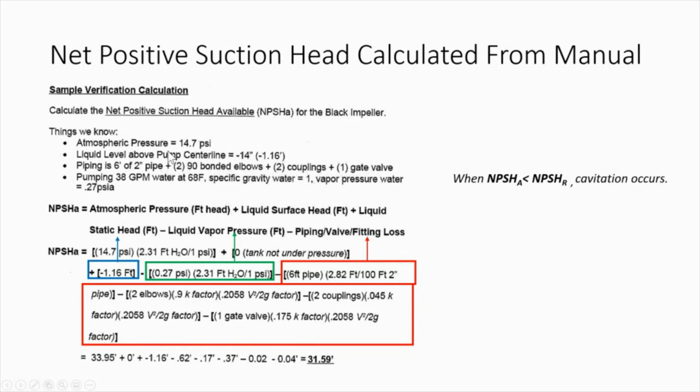But just remember one thing, that whenever you do a math, always keep your units consistent. For example, you have over here PSI, but let's say your static head, it's in feet, right? So you need to convert this feet thing into inch. Only then you can solve the math. So yeah, if you plug these numbers in here, you will get your result.